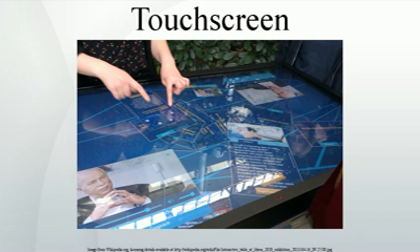Resistive touch is used in restaurants, factories and hospitals due to its high resistance to liquids and contaminants. A major benefit of resistive touch technology is its low cost. Additionally, as only sufficient pressure is necessary for the touch to be sensed, they may be used with gloves on, or by using anything rigid as a finger stylus substitute. Disadvantages include the need to press down, and a risk of damage by sharp objects. Resistive touchscreens also suffer from poorer contrast, due to having additional reflections from the extra layer of material placed over the screen.